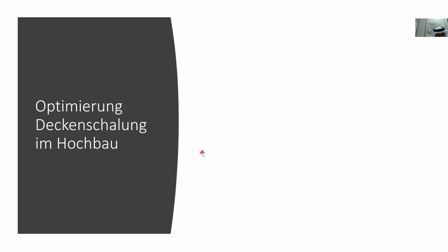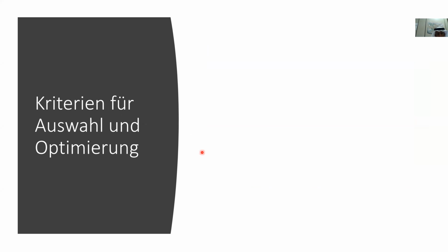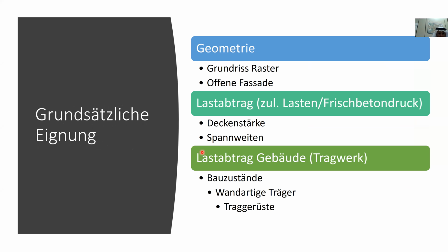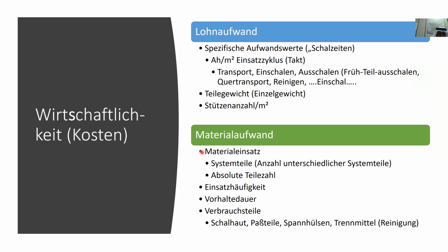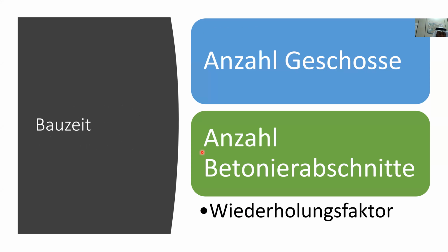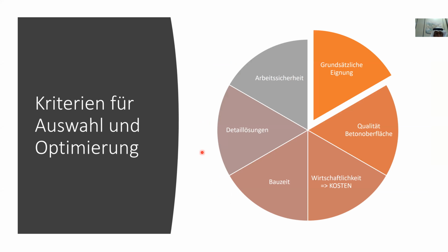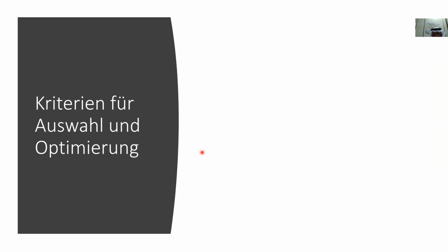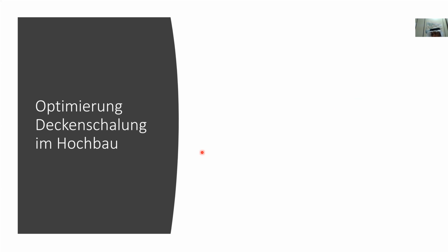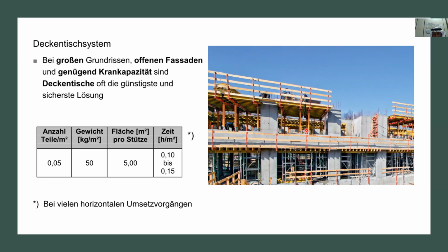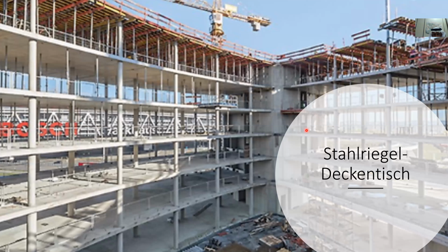Important is that you have to choose the correct type of formwork. Maybe we go back to these pictures. The best suitable type of formwork. As you can see here, you can use this only if you have space, if there's a repetition, if you have several floors on top, then you can use this.